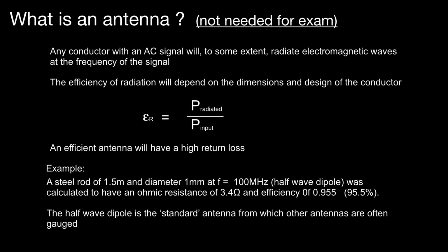decibels of gain with respect to the half-wave dipole. And it is probably worth memorizing the fact that a half-wave dipole has 2.17 dB gain, approximately 2.2 dB gain, on an isotropic radiator. So we'll have a little look at that in class a bit more.